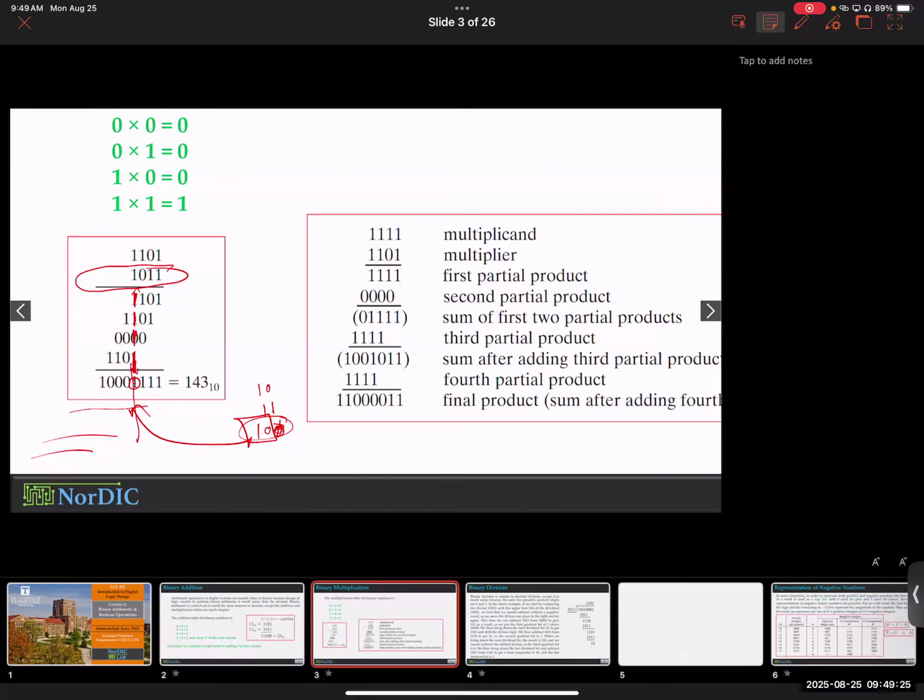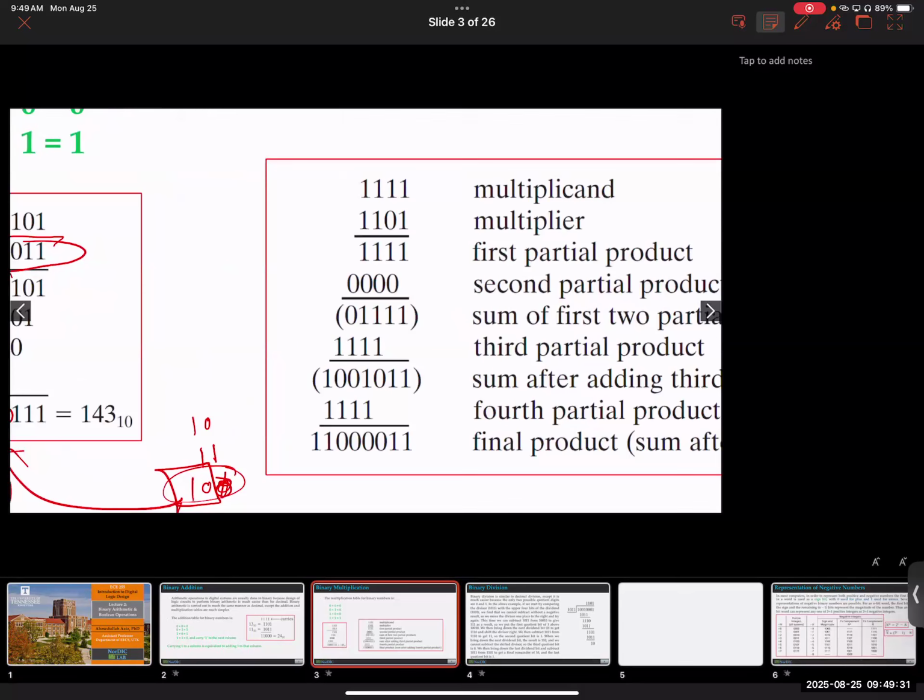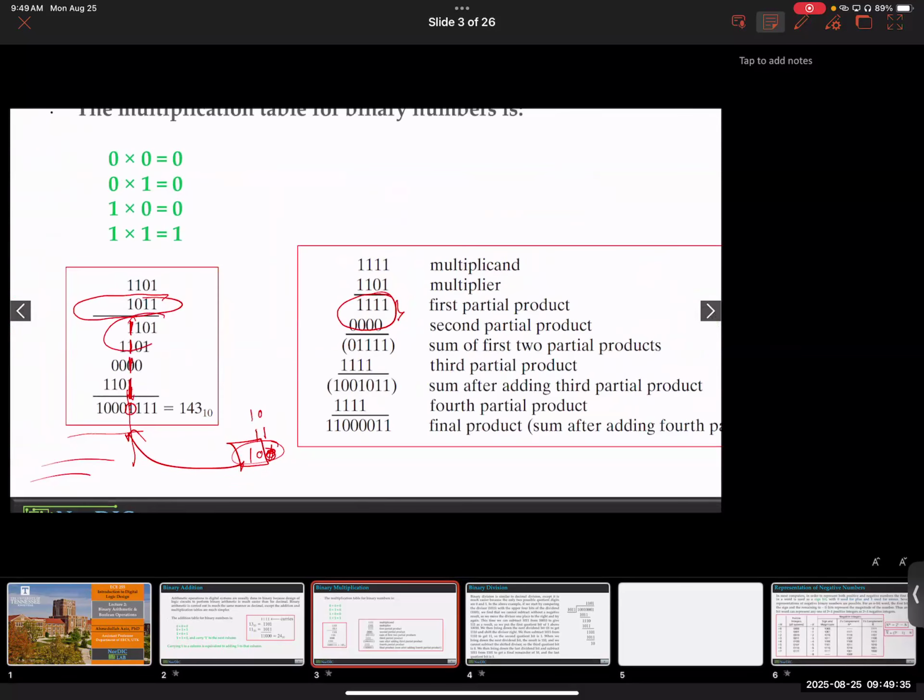So to avoid such a problem with overflowing carry, oftentimes in hardware design, we just add 2 at a time. For example, we take the output and add the next one with it. These are called partial products: 2 partial products at a time, and we add them instead of adding all of them simultaneously with an adder. This is a hardware decision.